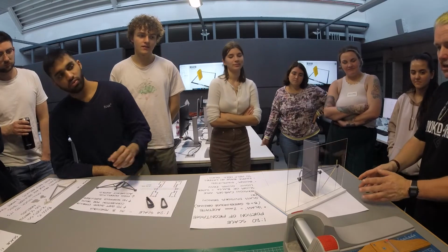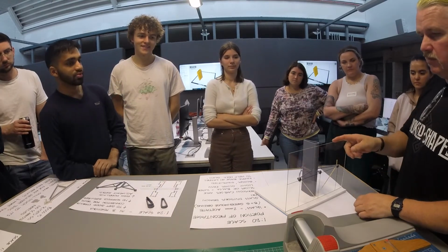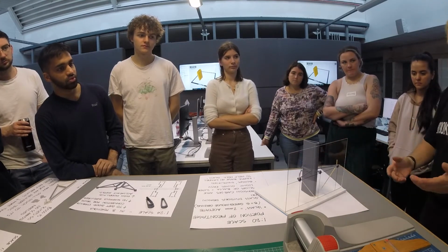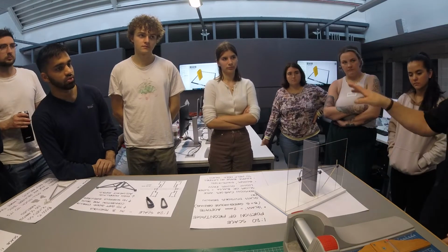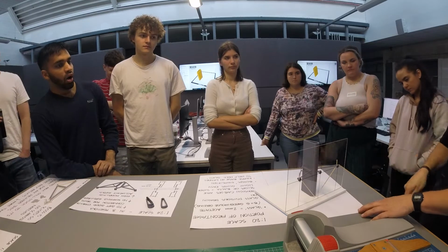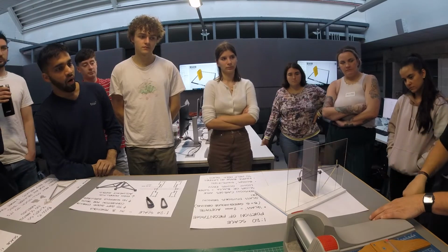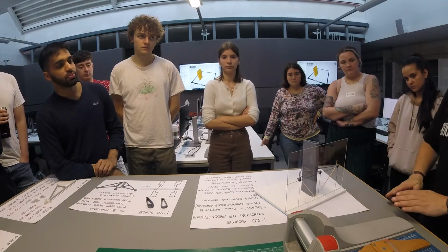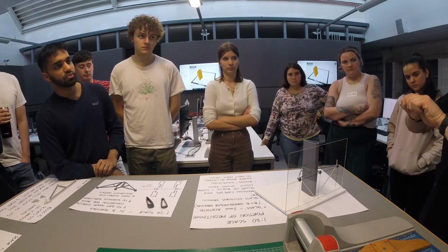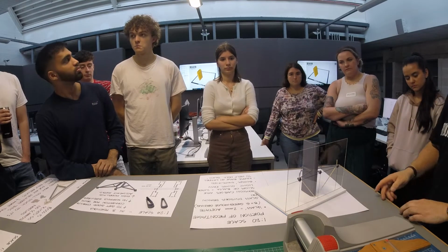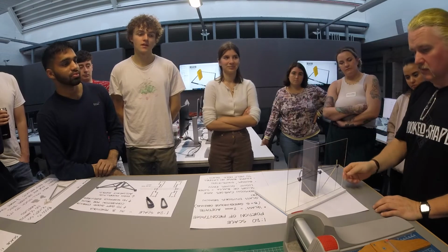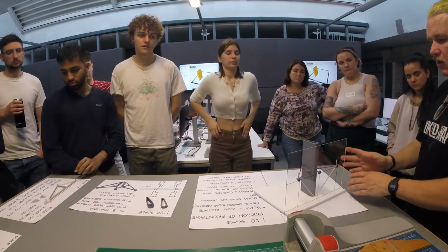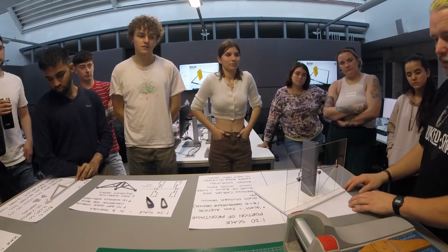It's really tricky to cut. You need saws or you need a laser cutter. But this stuff's really good, 2mm acetate, B&Q greenhouse, and you know they're 600mm by 600mm sheets, and all you need to do with that is score it. You can just run your knife across it about 4 or 5 times, get quite a deep score on it, and then snap it like when you see people breaking glass. You can start at one end actually, and it just runs down the glass. So there'll be failures. Mine was a bit rough on this side. If you run your finger down there, it's pretty yucky. Luckily, it didn't wreck my bit. It spoiled what was left.